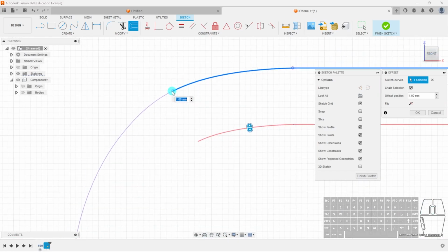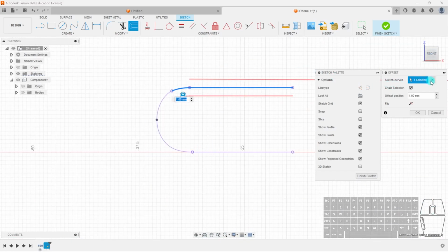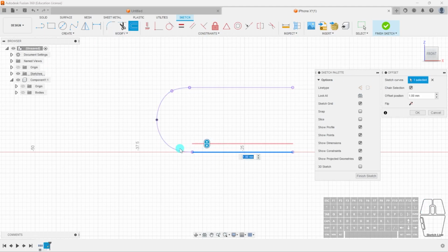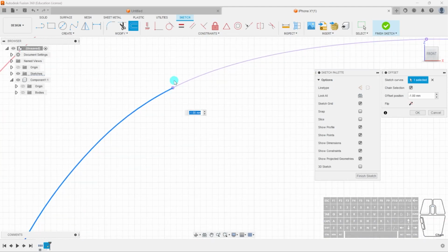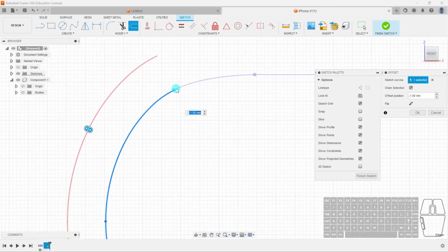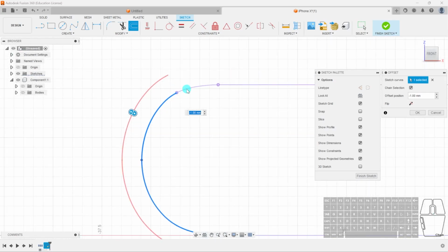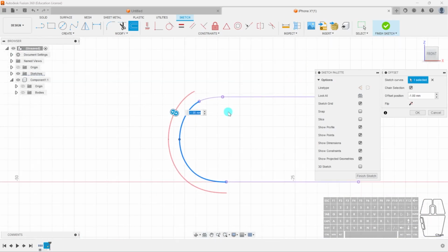Sometimes if you can't hit, that's fine. Offsetting can be a little bit finicky sometimes, I feel. Yeah, so it doesn't want me to do that right now. What I can do actually is offset out. Yeah, so the thing is, it's sometimes, remember with projections, they are not connected. The lines aren't connected. So unless they're connected, I can't actually offset it. So I'm going to just offset it by -2 outwards just for now.